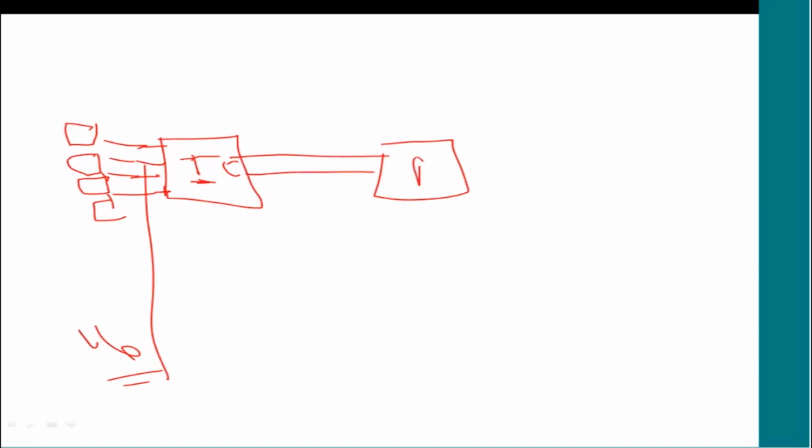This is ARM. Through APB or some memory mapped IO, it will be able to configure this to say, okay, these are the peripherals connected to the controller. I want this to be given higher priority compared to this. So you connect the peripherals according to the priorities of the interrupt inputs that the interrupt controller is programmed for. And then you can also selectively enable some interrupts. Some inputs you can disable. That means even if it generates an interrupt, the processor will not recognize it because the interrupt controller doesn't recognize it.